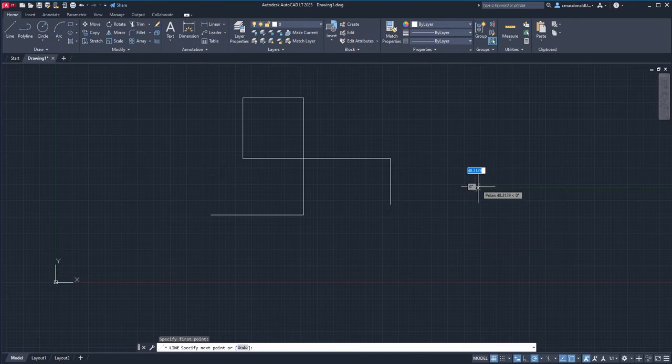Now let's left click, and as you can see, it's giving us the option for how long we want the length to be. So let's use 1800. Now instead of hitting enter, what we're going to hit instead is tab. So we're going to hit the tab key just to the left of Q and a couple keys below the escape. Tab. Now it produced the line of 1800 length, and it's freezing it at that length.